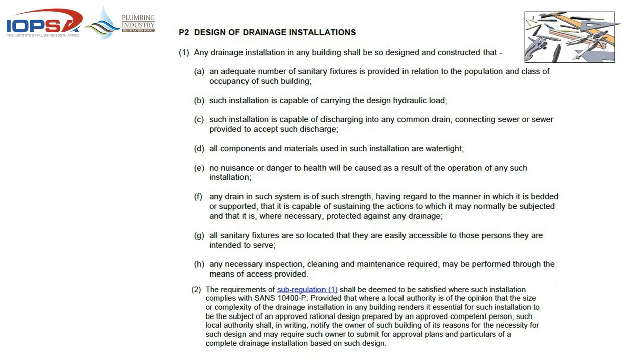All sanitary fixtures are located so that they are easily accessible to those persons that they are intended to serve, and any necessary inspection, cleaning and maintenance required may be performed through means of access provided. So I don't want to see pipes in front of the door. I don't want to see an access from my driveway.